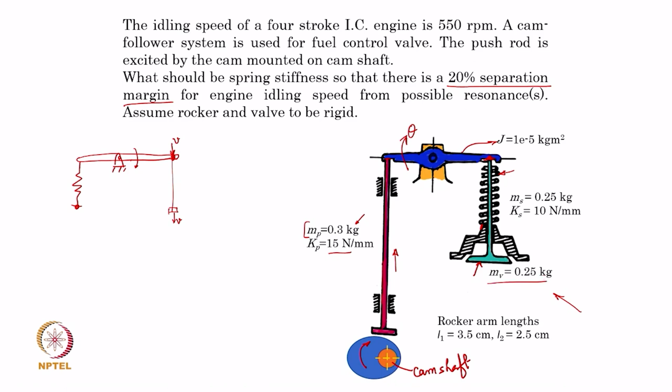So, kinematically it can be treated like a lump mass attached to the end of this rocker arm. For the sake of considering its contribution to the kinetic energy of the system, we can as well consider the valve mass to be situated here, because the velocities, whether you consider it here or here, are going to be identical, except of course if the valve itself deflects.